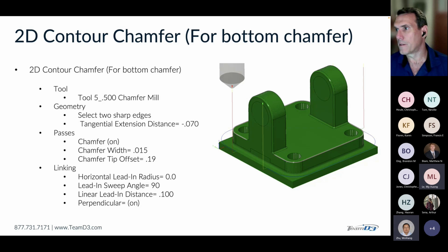I have a question on the tool set, the tool library that we used, because I saw all these parameters have already been set for us. Is it all coming in standard, or are these set up specifically for this workshop? The library that we're automatically finding is set up specifically for this workshop, and it's already embedded in the model itself. That's another thing that's kind of unique about Fusion: once you attach a library, or even if you use one of your standard libraries, as you use a tool, it kind of attaches itself to the design file itself. So you're able to access it more quickly.